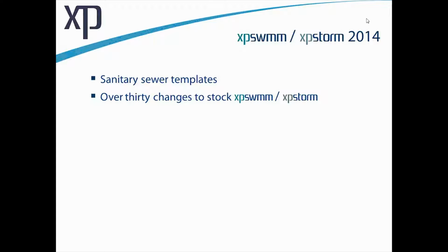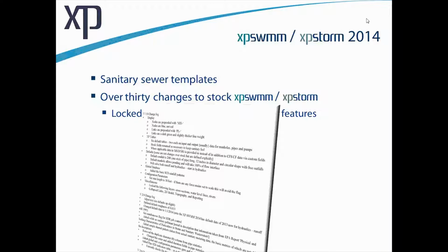So you've got setups in the database such as conventions to the manhole naming, tables set up for sewer modelling, and other adjustments to the interface so that you don't have to view the river modelling section and the 2D modelling section. And this also locks some of the non-sewer features, so it just means that you're not going to accidentally use them.